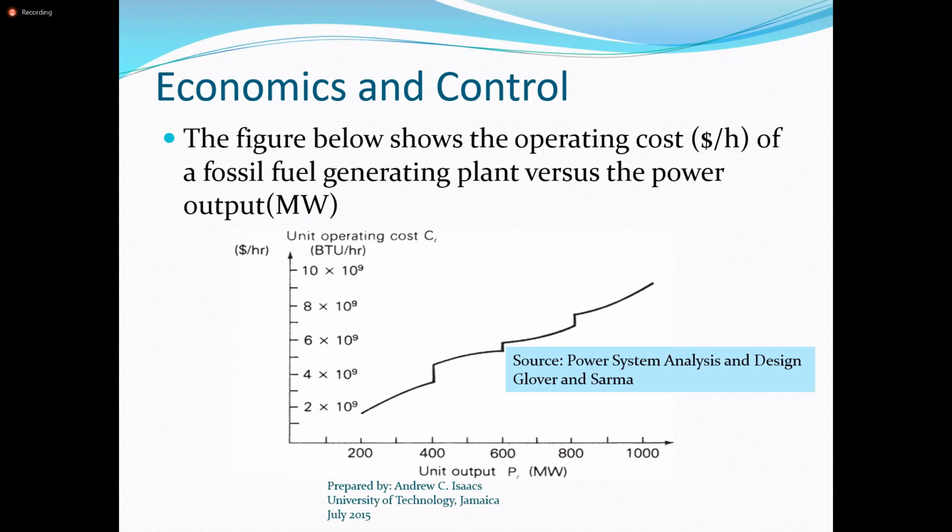I saw persons use words such as efficiency, and power factor is the level of efficiency of using power. That may have been stated in some piece of literature, but from a power system standpoint, that's not really what we are considering when we are looking at reducing reactive power.